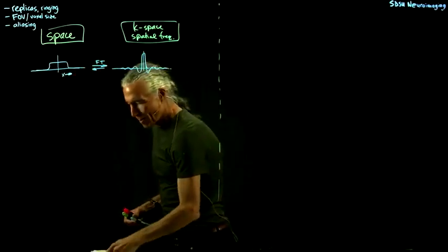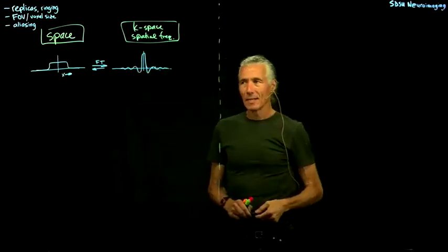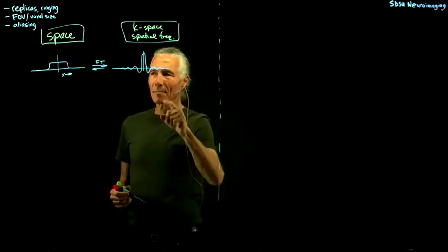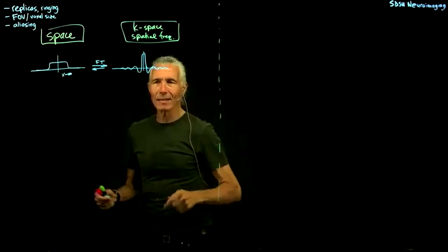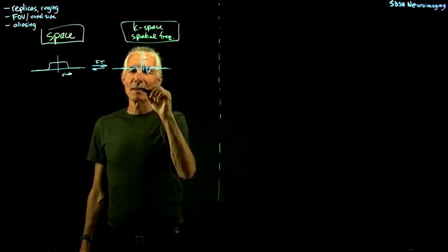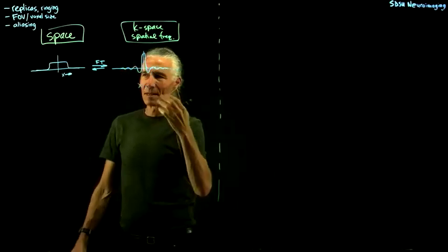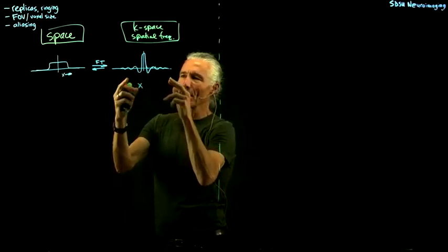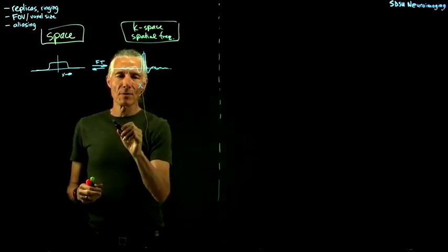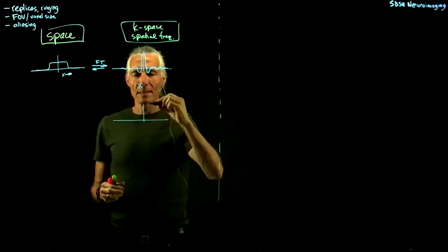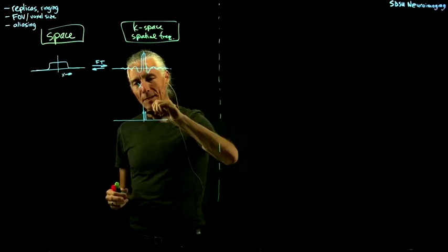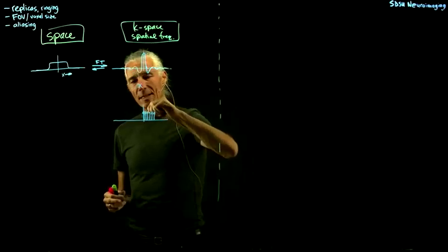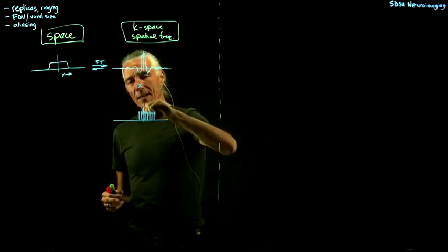And then what are we doing when we collect data? When we collect K-space data, we're discretely sampling the K-space data. And how can we represent that? We represent that in the infinite case. Again, we're making an argument with an infinitely finely sampled Fourier transform. And what we do is we just multiply by a bunch of spikes. Here's a bunch of spikes, and those are our sampling spikes, because we're instantaneously sampling a spatial frequency at each k point.